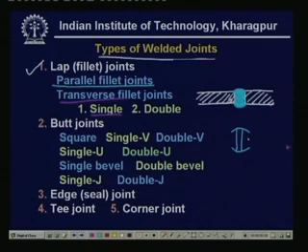Sometimes we use single V. The next type is single V. Let me draw. Here we use a single V joint. So, a V is formed by cutting the sides of this, and then we apply weld. So, the weld looks like this and the symbol here is, so this is the symbol of the single V butt joint.